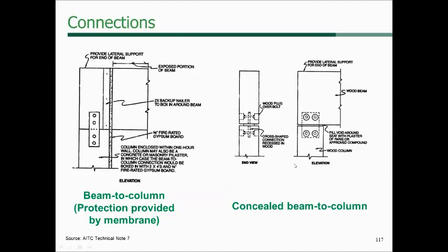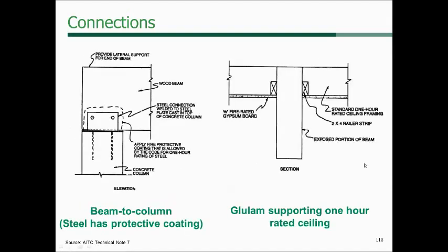This actually is a hidden steel plate that connects the beam to the column. The bolts are recessed within the wood member, and then there's a wood plug that protects that steel from being exposed to fire.